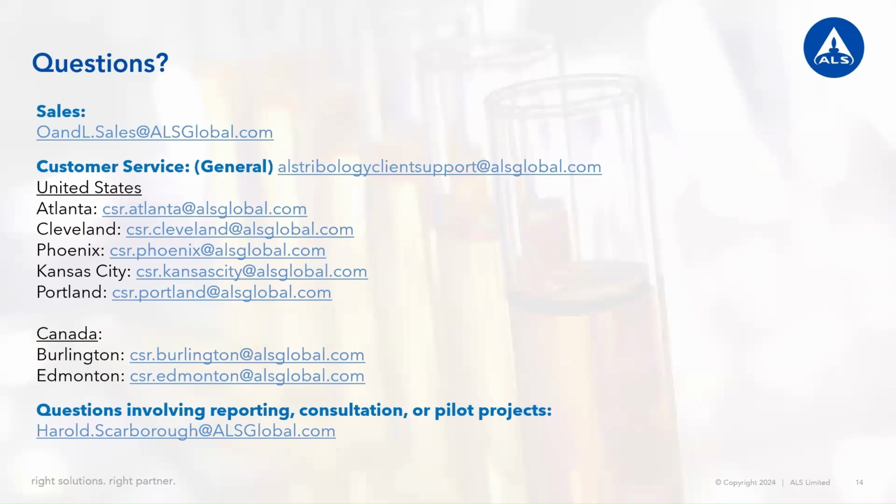So putting a conductance probe into the fluid, measuring whether we are seeing pulses and that type of thing occurring that would indicate that something is happening. And it would also depend on how that electric current is getting in. If it's something like a bad earth and you're just discharging through the engine rather than through the earth, those can be quite difficult to detect. Basically, the only thing that shows it up is the unexplained rise in metals.